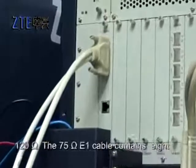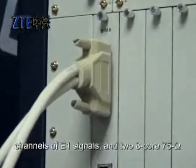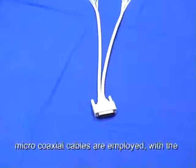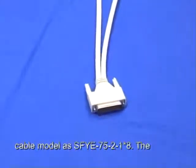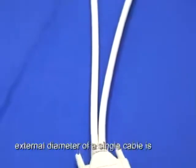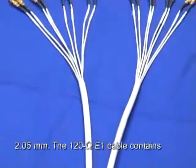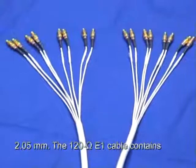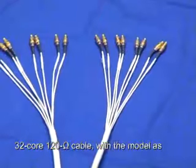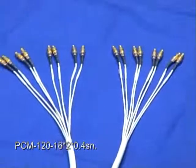The 75 ohm E1 cable contains 8 channels of E1 signals, and 2 8-core 75 ohm micro-coaxial cables are employed, with the cable model as SFYE-75-2-1x8. The external diameter of a single cable is 2.05 mm. The 120 ohm E1 cable contains a 32-core 120 ohm cable with the model as PCM-120-16x2x0.4 SN.